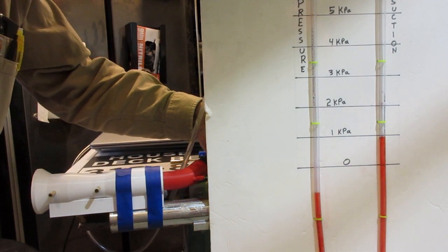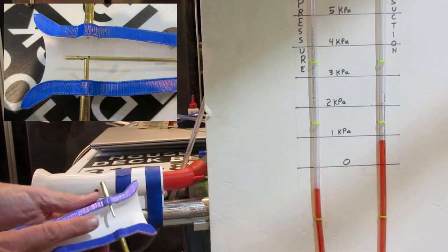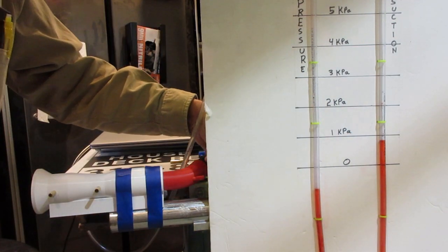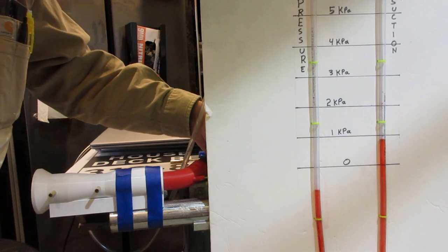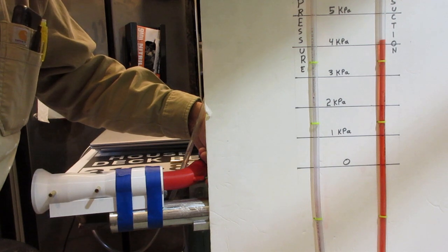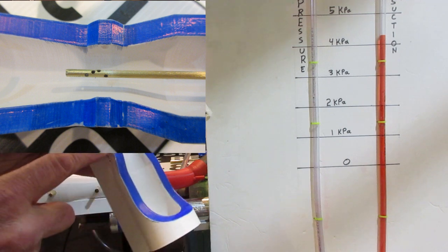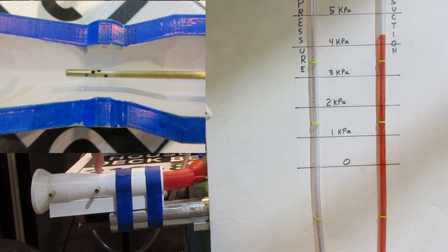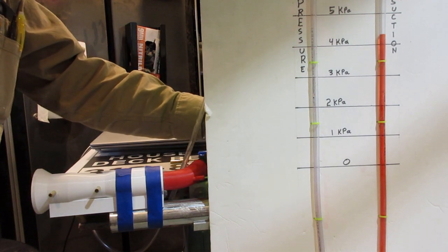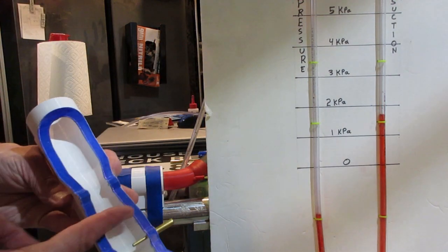Pull it back to the mark that lines it up with that first port, and you can see about the same suction we saw at that port. And we'll pull it back to the second port in the throat of the Venturi, and again we'll get just over 4 kilopascals like we got before, as we expect. All very nice and Bernoulli. And I'm going to slide it about halfway in between at a medium diameter, just to show you how you can pick up pressures at different points in the Venturi if you wanted to.